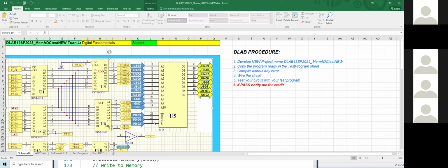When you have the address and the data, now you want to write into U5, so you apply pin 21 logic 0, pin 20 logic 1, and enable at 1, then 0, then 1. They just go to 0 to load data into that location and have to go back to 1. Otherwise, if it stays 0 and you change the address or change the data, they screw up inside.